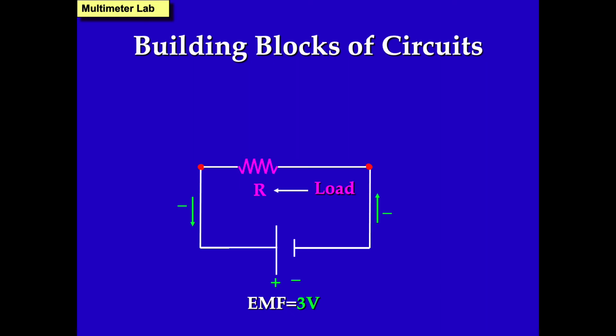The wires, we're going to assume that the wires are ideal, meaning that their resistance is small compared to R. So we're going to ignore what happens to the wires, even though that's not really true. Real power supplies and real batteries have something called an internal resistance.